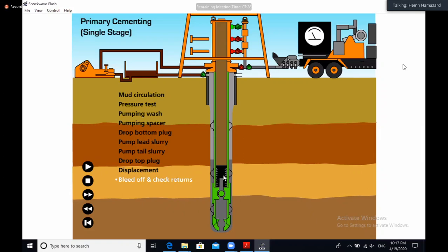The VAM top is a double seal. Like I said, online I cannot show you, but if you take a look, just visually, at the thread, you can know this is VAM top and this is buttress thread. VAM top has 2 seals, so it's giving more meaning for sealing, for hydrocarbons, for H2S, for gas, for corrosion. So briefly, we use VAM top connection for lower sections and buttress connection for upper sections where we don't have any oil and gas. Thank you.